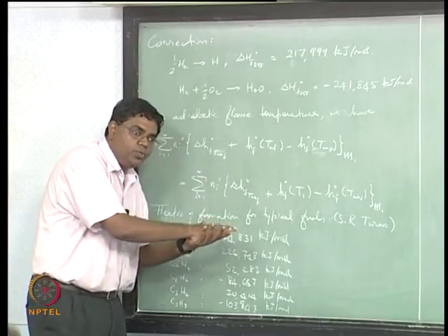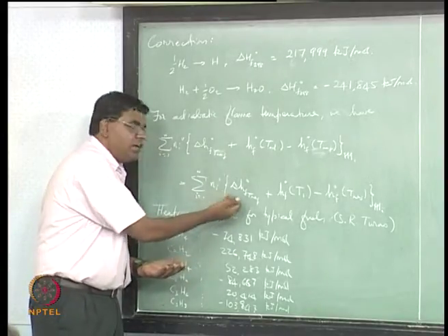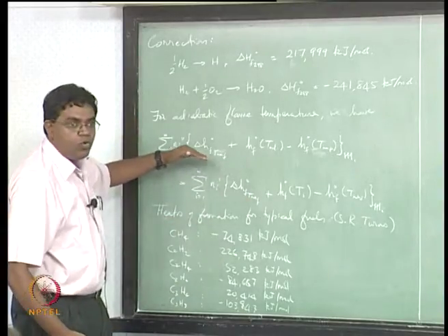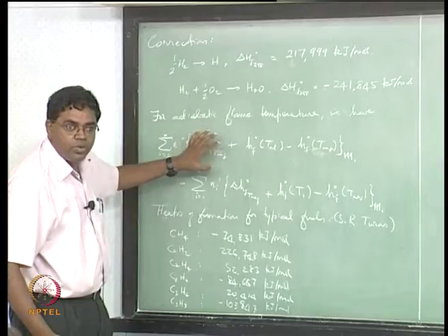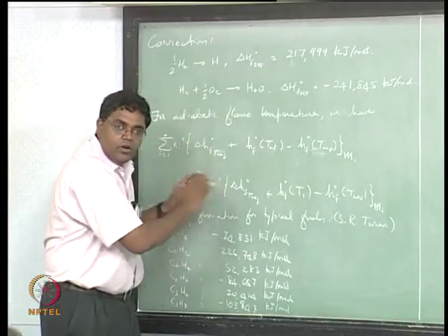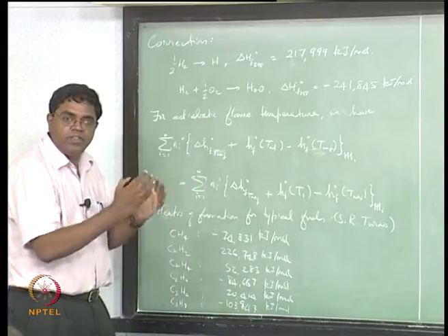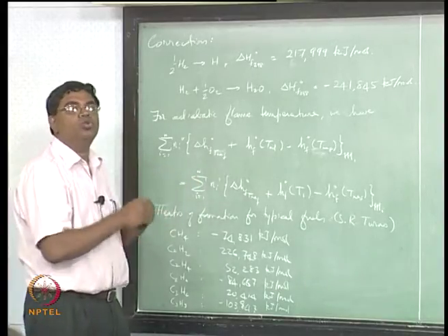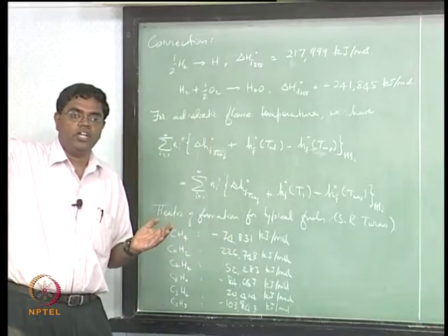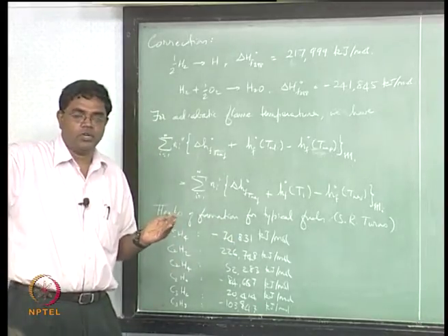Keep that heat with you, supply some heat for unwrapping the bonds to get the reference elements, and then get the reference elements to form the products. You get a lot of heat over here, a little bit of heat over here, and you have supplied some heat over there. All that now adds up to some net heat that is available to you, which you dump on the products to raise their temperature all the way to the adiabatic flame temperature, whichever temperature they can go to.